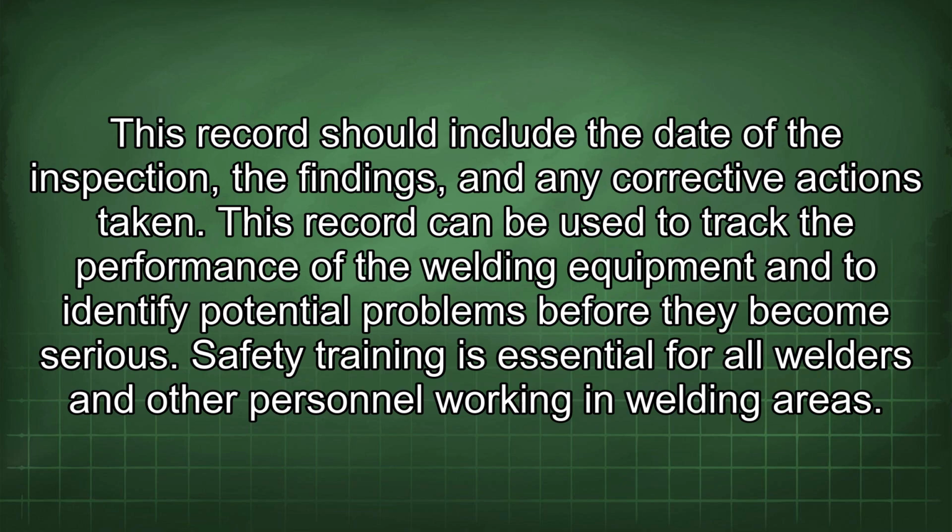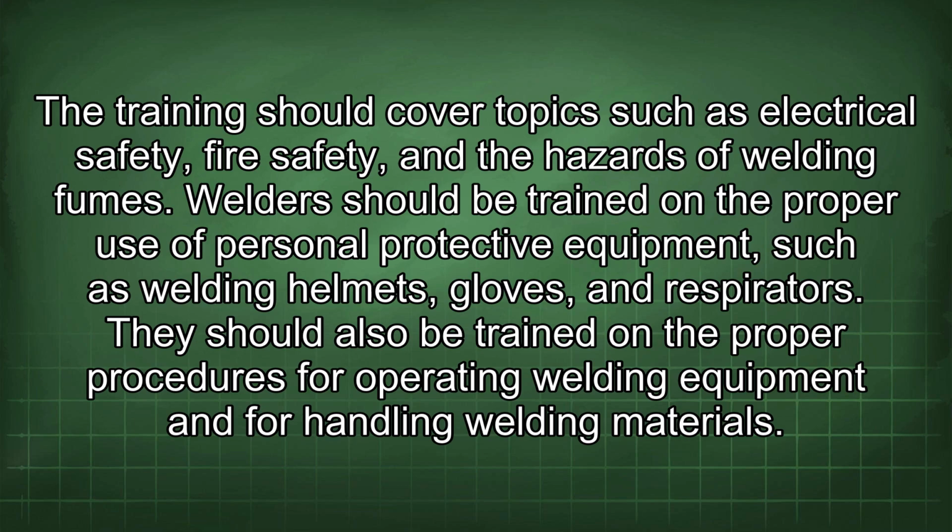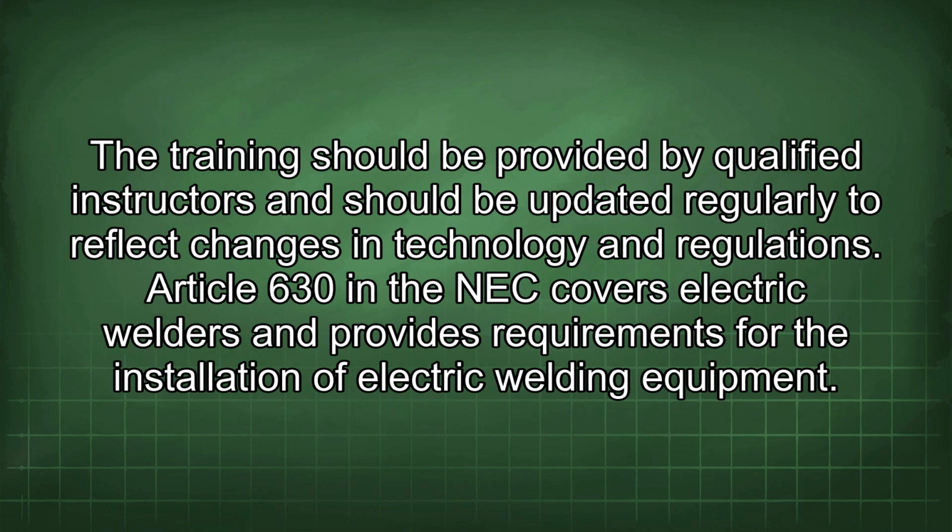Safety training is essential for all welders and other personnel working in welding areas. The training should cover topics such as electrical safety, fire safety, and the hazards of welding fumes. Welders should be trained on the proper use of personal protective equipment such as welding helmets, gloves, and respirators. They should also be trained on the proper procedures for operating welding equipment and for handling welding materials. The training should be provided by qualified instructors and should be updated regularly to reflect changes in technology and regulations.